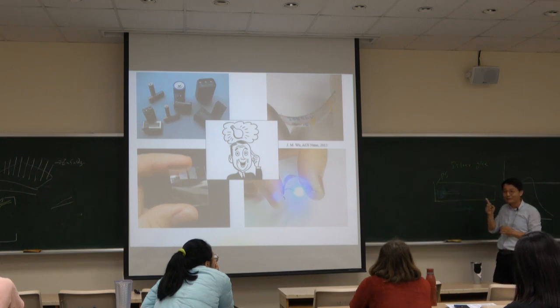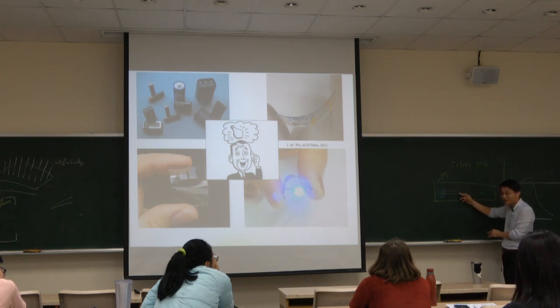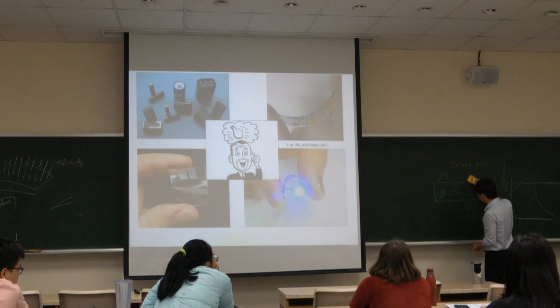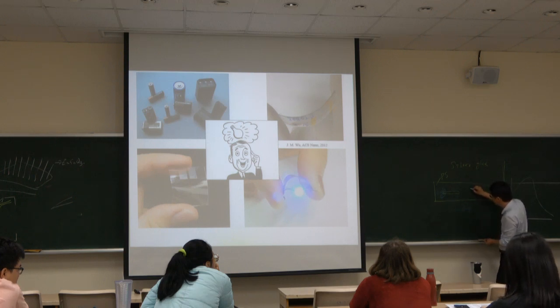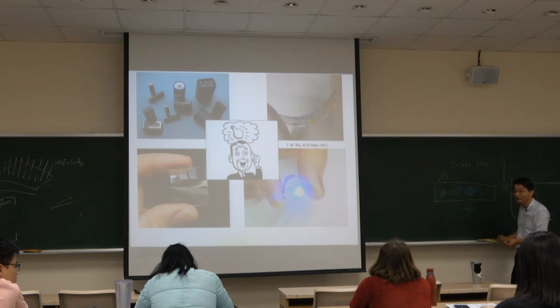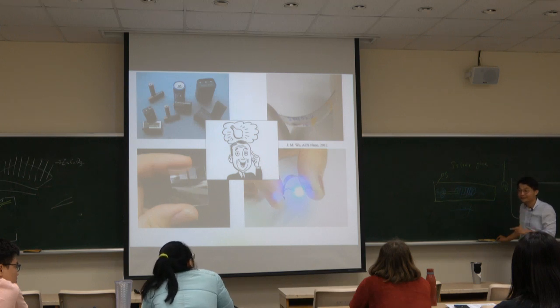And then you make one point of the electrode, and then another is this point. This point is quite important. If you drop too big a drop, it will fully cover. Do you understand? So you have to be very careful dropping this silver glue here. Then this silver glue will diffuse to here. Once it diffuses to here, you have succeeded. Both sides have a conductive electrode.